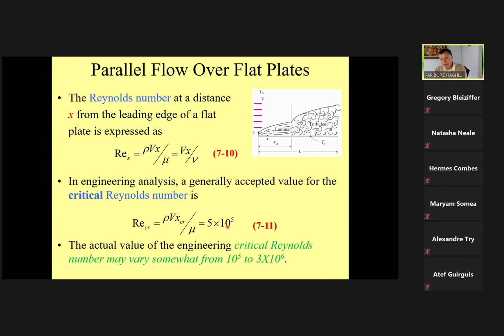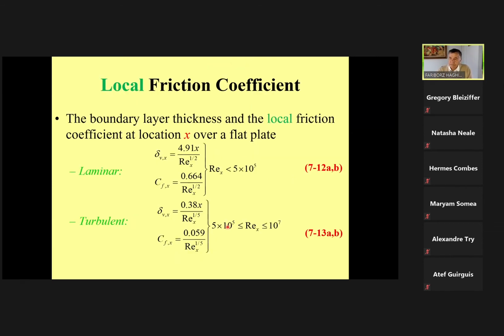Therefore, now we again have an indicator, the same as in fluid mechanics, for which range of flow is laminar and which range is turbulent. Again, these are drag force expressions that you can read, but I'm focusing on this one part. We have seen it before. This is the thickness of the boundary layer. Remember, we had the boundary layer thickness for velocity, and we have a boundary layer thickness for the temperature.